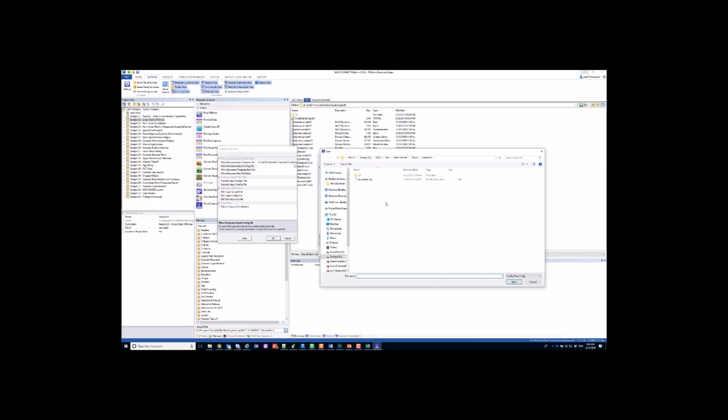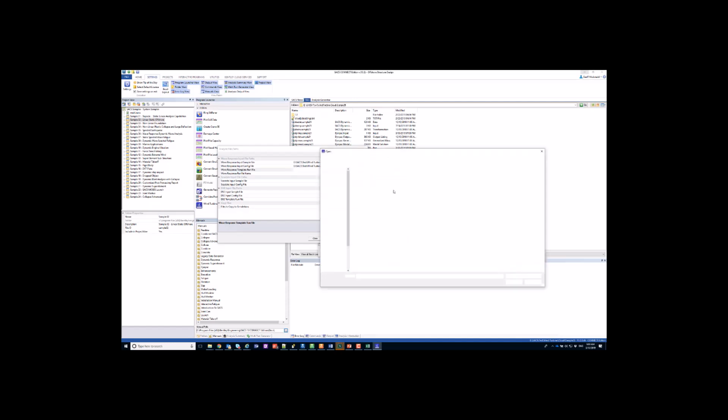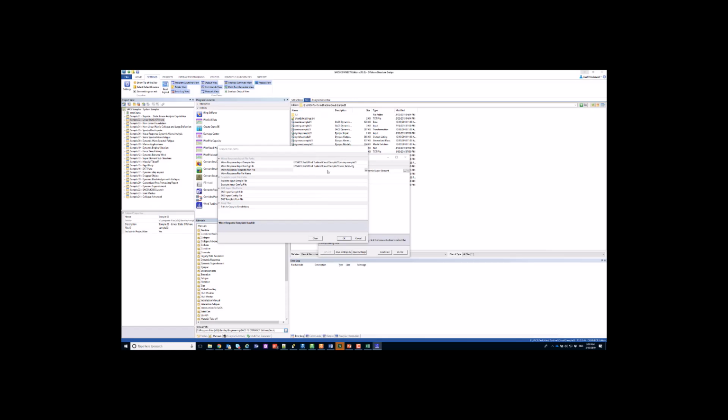All right, we're going to have these. We have this SACS fields.cfg file. I'm going to open that up and show you. But this is just a configuration file to show what that input file is going to look like. And then we're going to have a run file for that wave response analysis. So we have a template for that. And then this is going to be our new run file name that's generated. So it's just going to take the one that you've selected here, but it is going to allow for you to select a different name if you'd like.